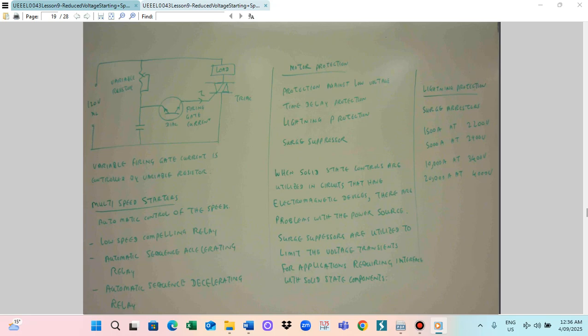The voltage surge can especially be created by coils, because induction motors are coils. The motor coil can easily create harmonics and voltage spikes. Those voltage spikes can damage the motor. Because of this, we have to utilize a surge suppressor. Surge suppressor means any switching surge needs to be suppressed. Lightning protection equipment also needs to be utilized. This is important for motor protection.